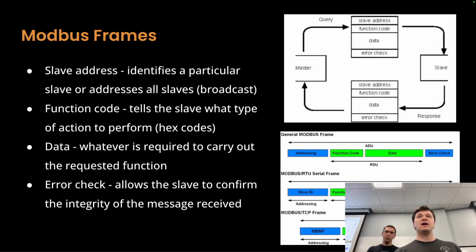An error check. So this is a redundancy check, and there are different ones depending on the specific communication model for Modbus. So you might have a different one for Modbus TCP, and you might have a different one for Modbus RTU.